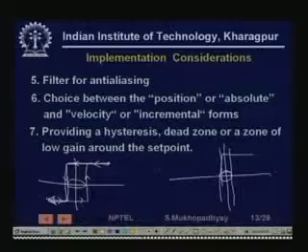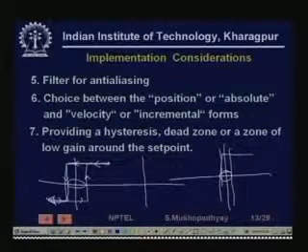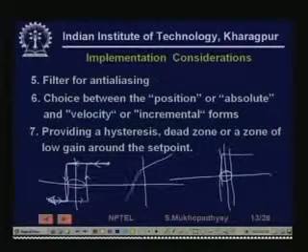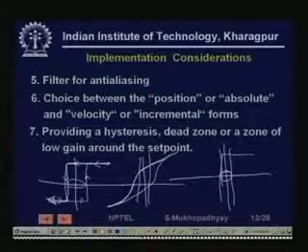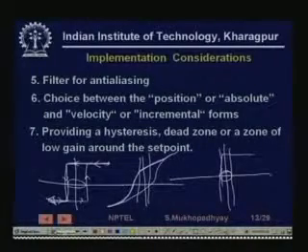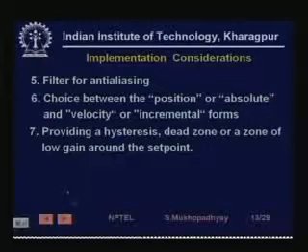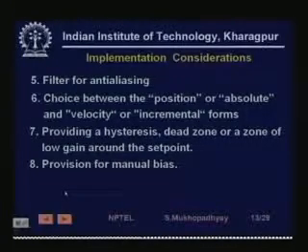Now, you can have a smooth hysteresis comparator, you can have something like this also. So, you say that I am going to keep the gain and then slowly change the gain. So, in this zone the output is not switched. So, these things can be done to avoid noise, of course, because maybe you can actually tolerate that much error, and otherwise it will unnecessarily be moving the actuator all the time because of noise. So, for some actuators this may not be good.